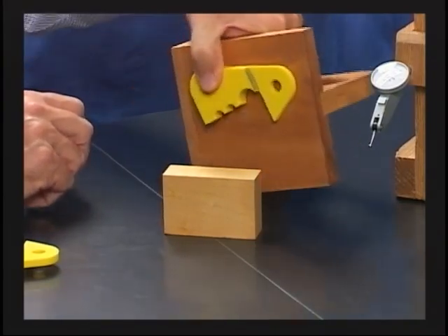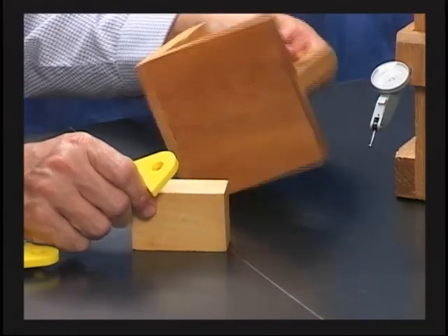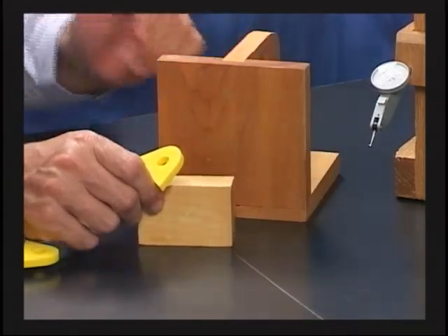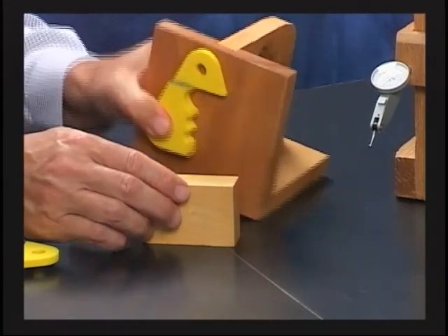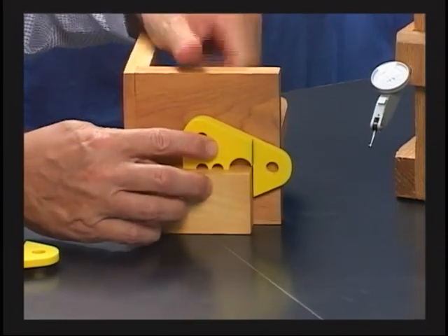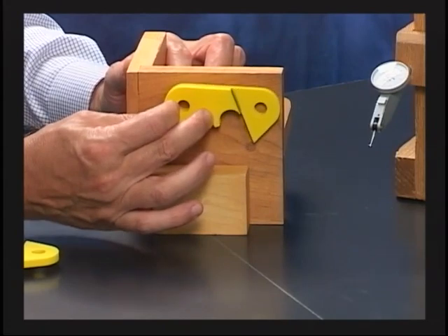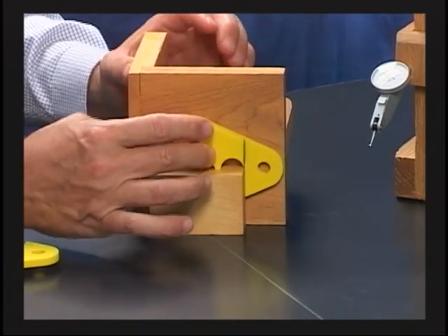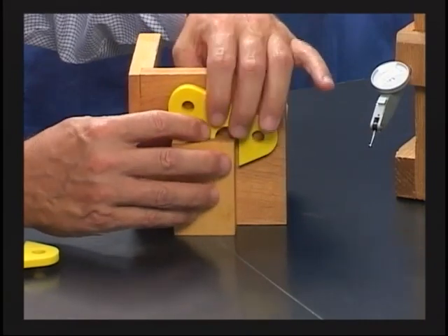I might take the angle plate. Remember how this angle plate is 90 degrees. Any way you turn it, 90 degrees. We know it's calibrated on a periodic basis. We know that it's good. So I might take this part, turn it sideways here, bring it down to this top surface. It's lined up on the gauge block now. You notice that basically on this one, it's a simple one. I have primary datum, and I'm bringing it down to my secondary datum. It's locked on. And what I'll do is raise mine up here a little bit.